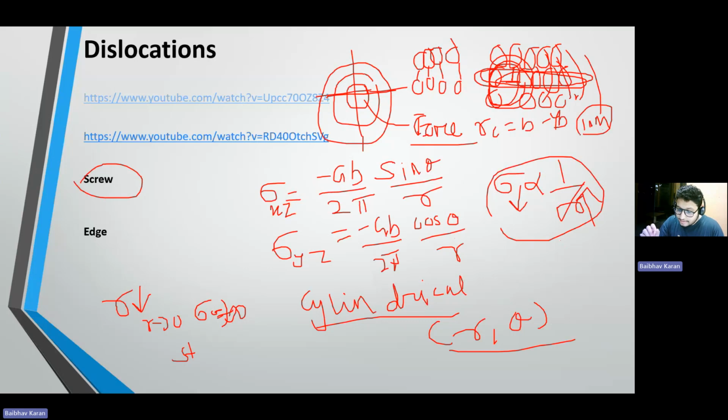And these energies are elastic energies, which are formed due to distortion of nearby crystal planes as they accommodate the dislocations. That means, as I explained earlier, there will be disturbances in the bonds around the dislocations, and these disturbances give rise to elastic energy. Did you get my point?